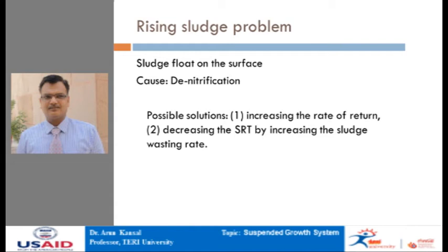So, what is happening is that the sludge, which consists of highly active microorganisms, this is activated biomass, goes to the bottom of the tank, and here we generally have no oxygen available. So in case the wastewater is nitrified, the moment it enters into the aeration tank, this is the top level of the water. This is the zone of the sludge. Treated water is coming out. This is the sludge recycling line and sludge wasting line. So this is a typical secondary settling tank of the activated sludge process.